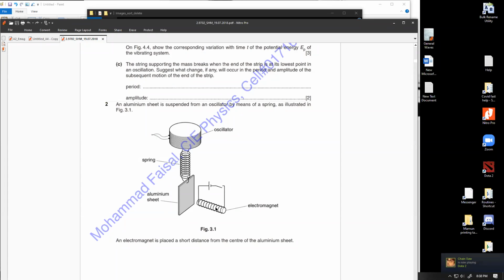This is the DC solenoid, and here, as the aluminum sheet will be moving, this thing is very much similar as the rotating disc. When the aluminum sheet is going down, those electrons are going to produce the current within. So there will be eddy current produced in the aluminum sheet as long as it is at some movement with respect to the electromagnet. So each of those motions, downwards or upwards, we will be having eddy currents in opposite directions, which is going to slowly eat up the kinetic energy of the aluminum sheet and convert that into heat energy. So that way, we're going to have much stronger damping effect, or the vibration will die out much earlier. This is the effect of those electromagnetic thing.